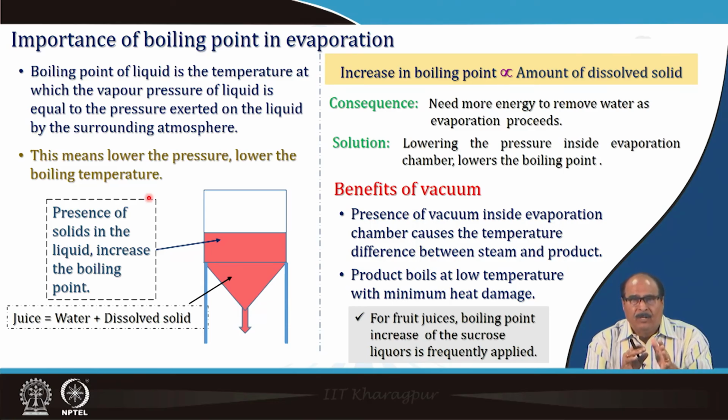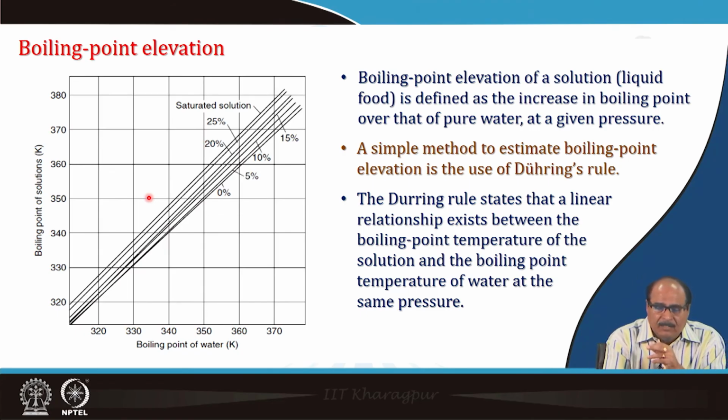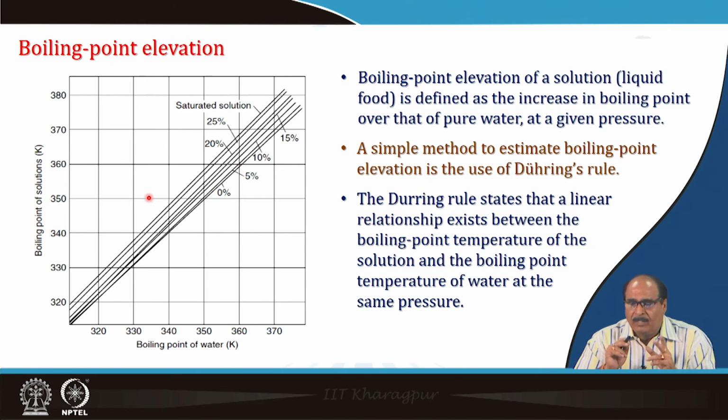Okay. And for fruit juices etc., boiling point increase of the sucrose liquors is frequently applied, and it is always beneficial as far as the product quality is concerned. Boiling point elevation, you can see here in this figure, there is a linear relationship. Boiling point elevation of a solution is defined as the increase in the boiling point over that